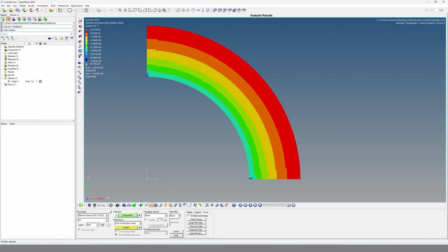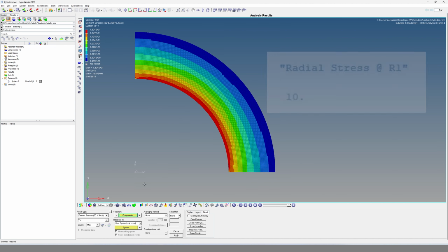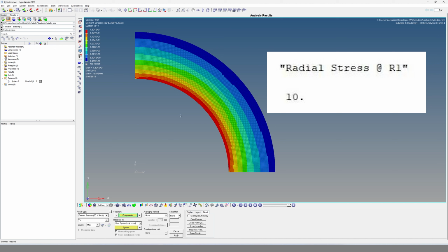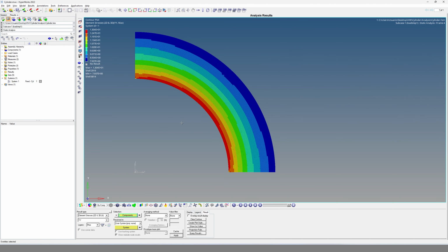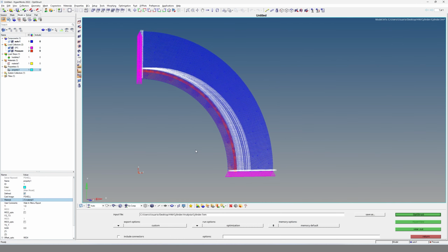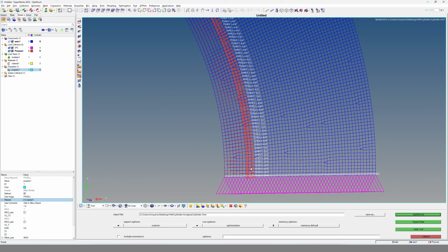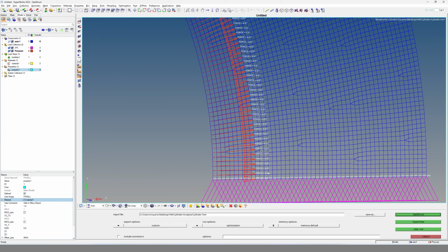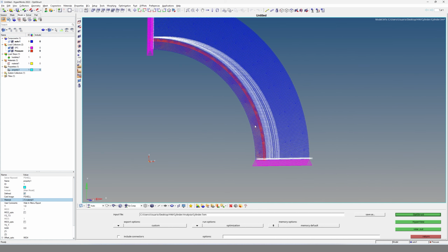As you can see, in the radial direction we have a value of 5 at the inner radius. So this is half of the stress that we should be getting. I realized that for the formula for the forces, we actually applied half of the value of the forces, because I calculated the perimeter as pi times the internal radius, which is not right. It should be pi times the internal diameter. So let's update the value of the forces.